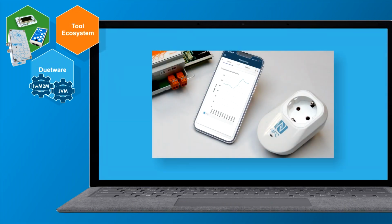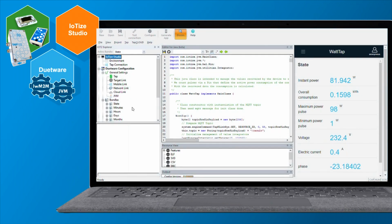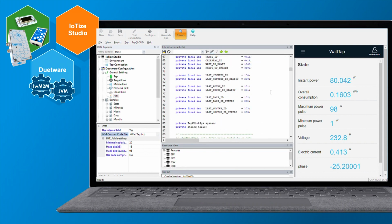This example, called WattTap, measures electricity consumption. It uses the module's GPIO to communicate directly with electrical components. It also has an edge data processing routine in Java that logs electricity consumption in the module's memory. Here, the module's configuration references the Java routine that is executed by the JVM and allows us to create variables we need in the module's memory, to store data, and to update log data using a generic scheduling routine.